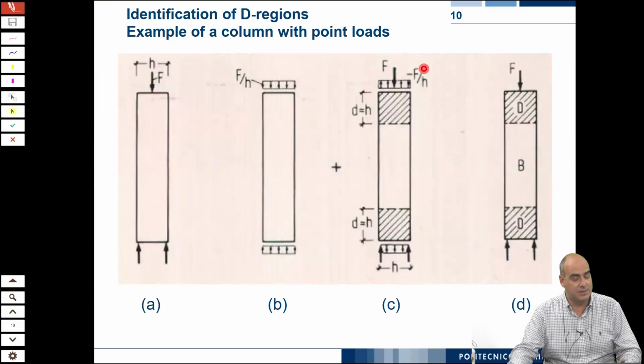This allows us to say, okay, what is the resultant of this system of forces and stresses? We have just said before, 0. So at a distance from this cross section equal to the side of the cross section, at a distance h, you actually only feel the effect of the resultant.